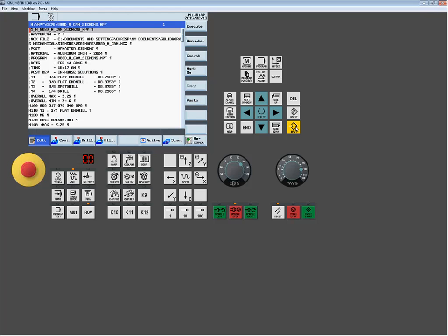Now I'm going to create tool 2. Tool 2 again is an end mill. I said it's a 3/8 end mill, so I happen to know that the radius on that's 187. And our length. I'm going to do a third tool, which is going to be a drilling tool, tool 3. Tool 3 in this case is a 3/8 diameter spot drill. So again, 187. I don't necessarily have to give it, obviously, the radius for a drill because there's no cutter comp associated with it, but I can. Sometimes it's nice from a reference side.